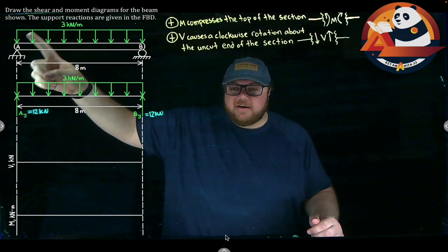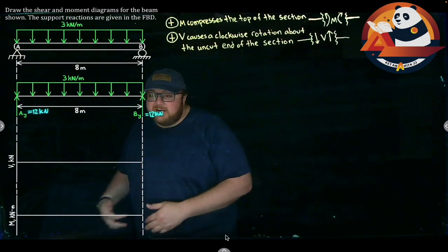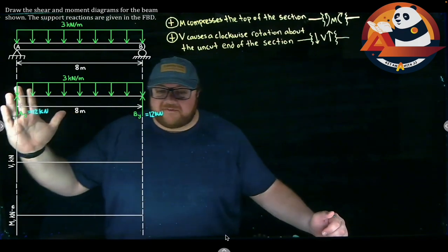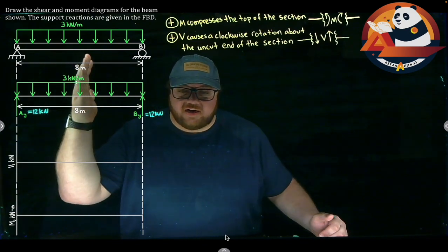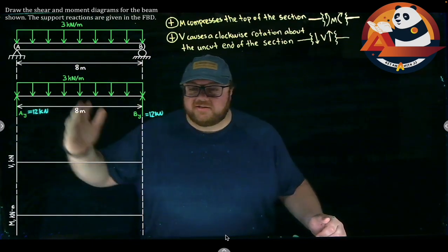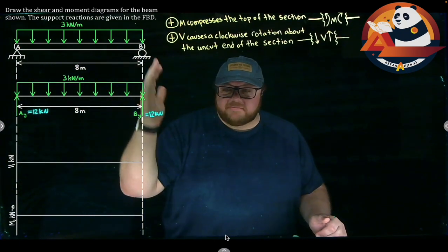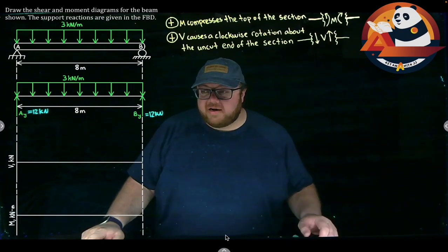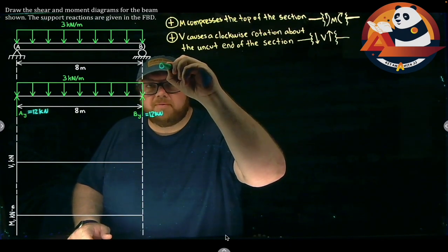So we're trying to find our shear and moment diagrams. To figure this out, we need to figure out where our loading changes. We work left to right across that. Anytime we have a distributed load starting or ending, a concentrated force, or a couple moment applied, we need to make a new section. So as I leave A, everything stays the same until I'm at the right edge of my beam. Really, I can do this in one interval here. So this is one interval for our problem.